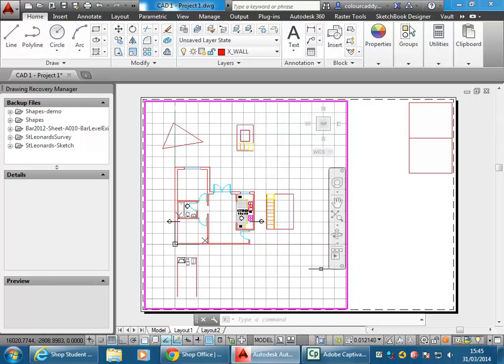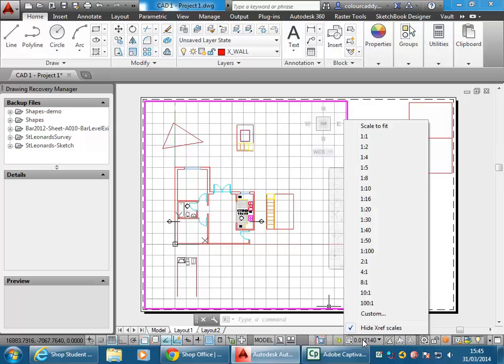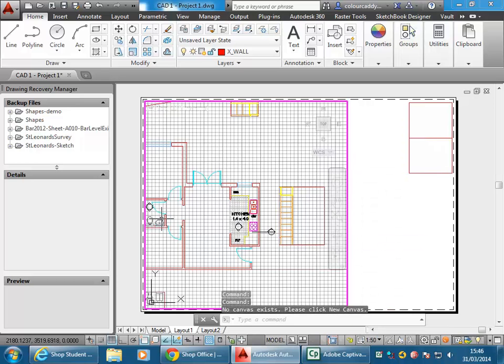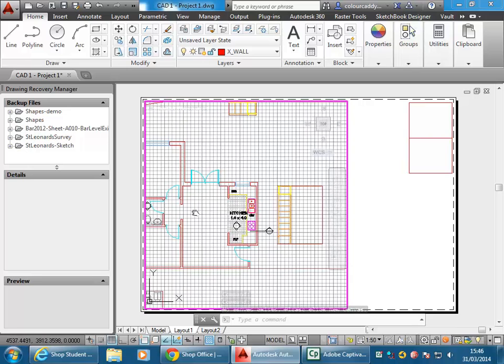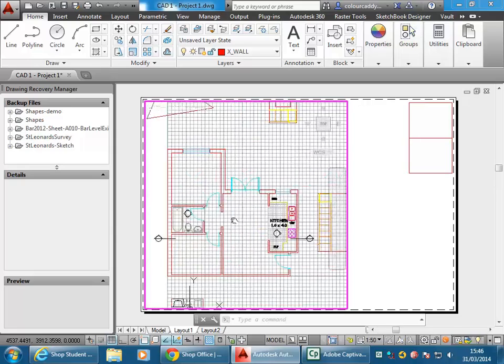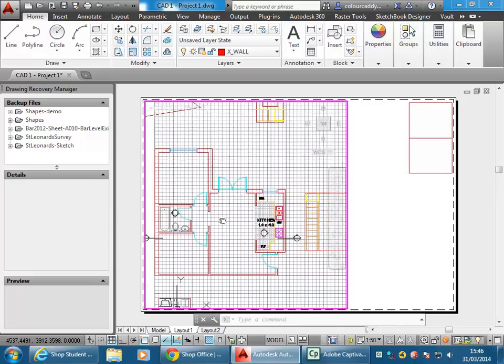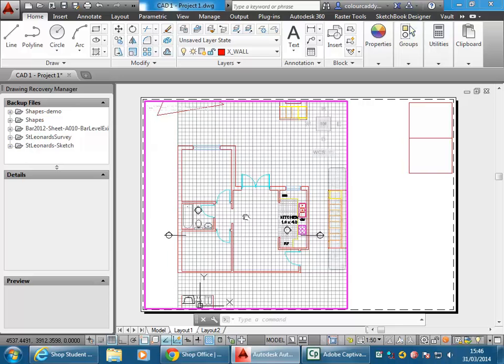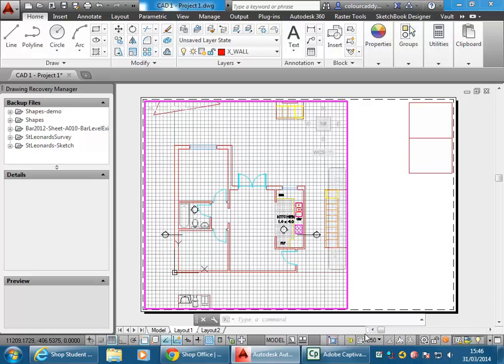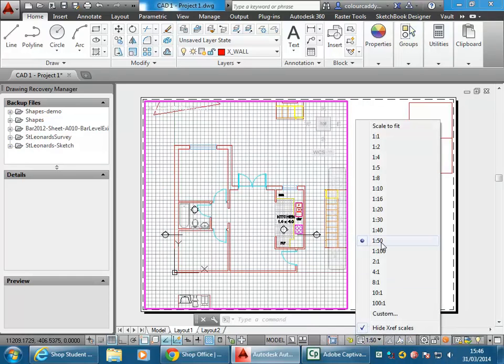So you've seen the scale option back in your model tab. When you choose it here, it's a little bit different. It's setting the scale of that viewport. And so here, if I choose 1 to 50, that's setting the print scale. Okay, so then you can see it's zoomed just a little bit, but that's all it needed. And if I pan, that'll move the objects, or sorry, move the view. But it's not changing the scale. You can see it's still telling me it's 1 to 50.